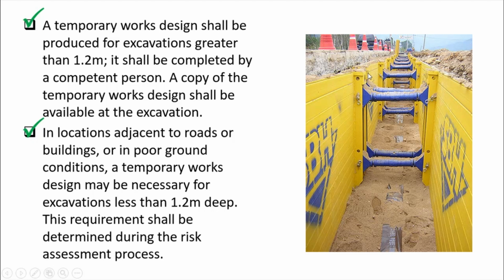Okay, so even if this is less than 1.2 meter, because of the existing hazards on the location, like the building beside the excavation that may introduce additional load to the excavation, the temporary works design is also necessary on this excavation.